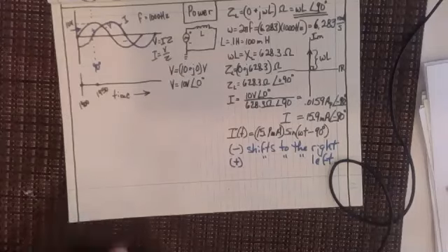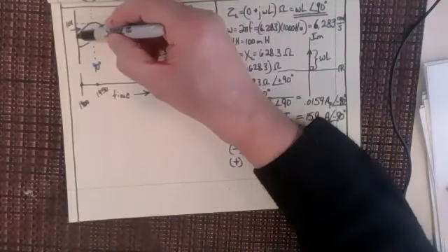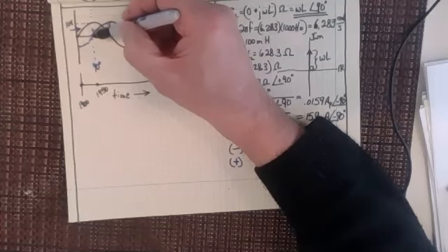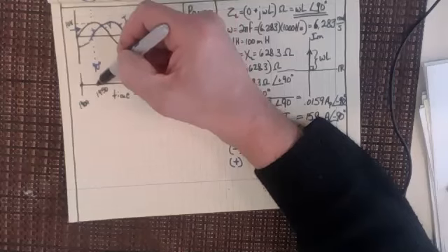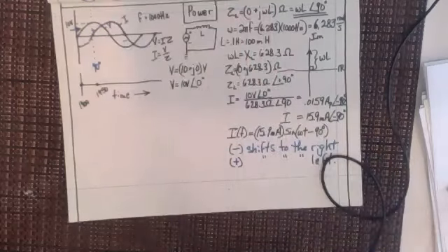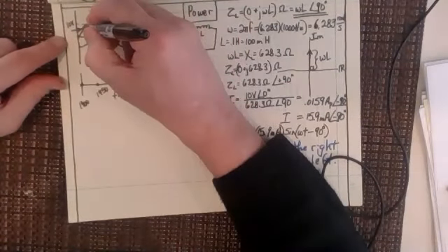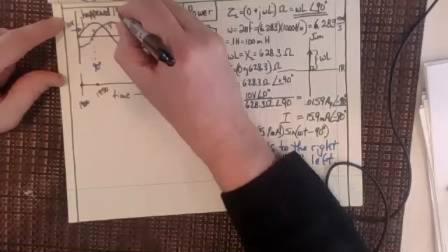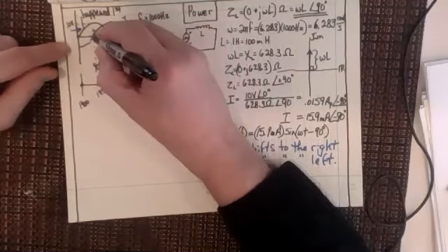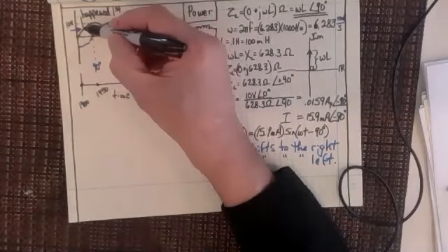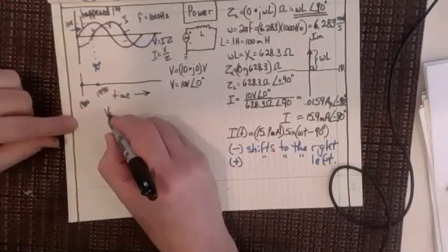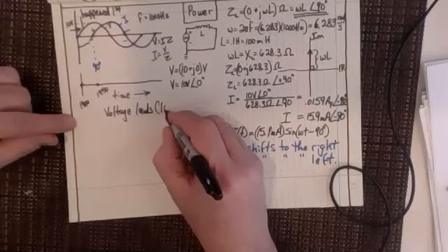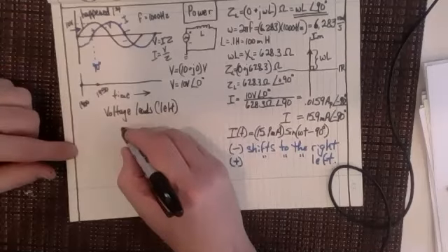And that's because it's coming later. The first thing that happens is the voltage waveform. The voltage waveform starts here in 1900, let's say, and then starts going up. In fact, the current waveform doesn't even start until this one is already up to 1950. So you can see it's later in time. That's what I'm really trying to point out, is that this one happened first. And then this happened second, right? So the voltage is leading the current. Voltage leads, and that means to the left, current.